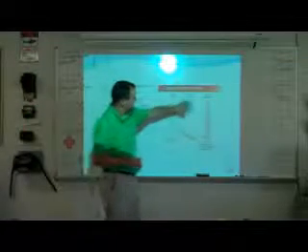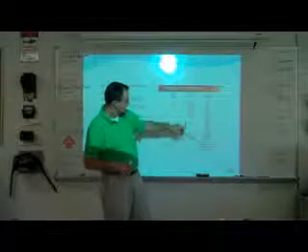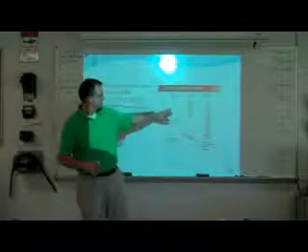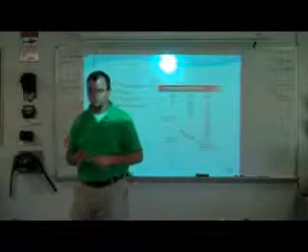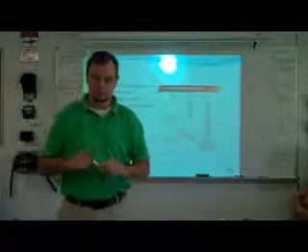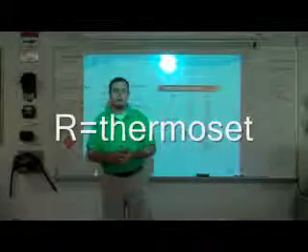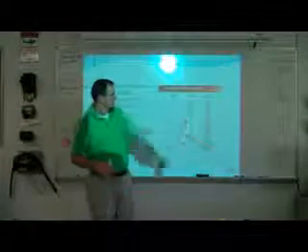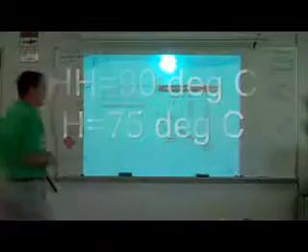So you kind of look through here. You can see all the different types. You've got RHW, THHW, THW, THWN, XHHW, USE, UF, and so on. RHW: what does R stand for? Remember when I wrote it up earlier? What type of insulation am I talking about when I talk about R? Thermoset, right? And T is what? Thermoplastic. Very good. Two H's? High heat. One? Heat. W? Wet.